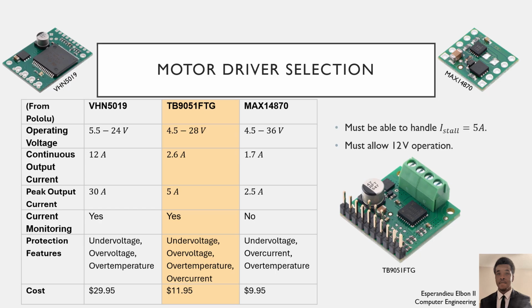Motor stall current is the current a motor draws when it is stalled. It is important that a driver be able to handle this at 2 points in a motor's normal operation. At the beginning, when a motor starts up, because it will momentarily draw its rated stall current as it starts to overcome its initial resting state, and at any point when a motor stalls and it becomes unable to move.